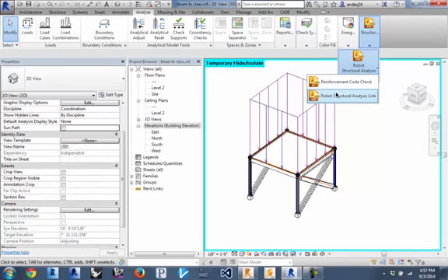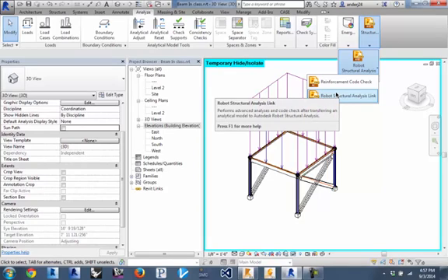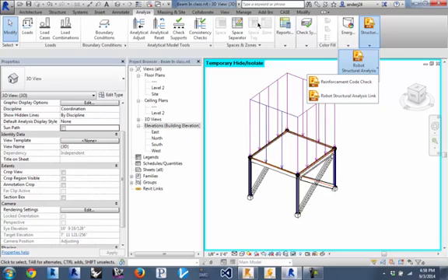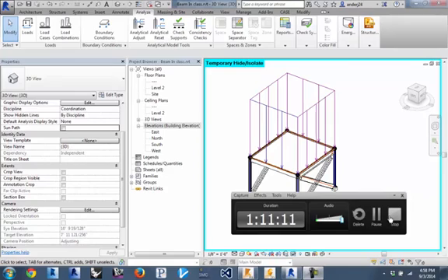All right. So the next step would be to bring in the 5 floors, or if you want to start with 1 floor, sort of analyze that. The idea would be to set up that group, you want to grab the columns, the central wall is going to be a little bit different, and then run the analysis on that and see what you're getting. Right now we're just looking at either live load or dead load. Obviously, it gets more complicated with factoring in wind loads and all that. So if there's no more questions, thanks, Jason. Cool. I'll go back through this once more and can help reinforce it.